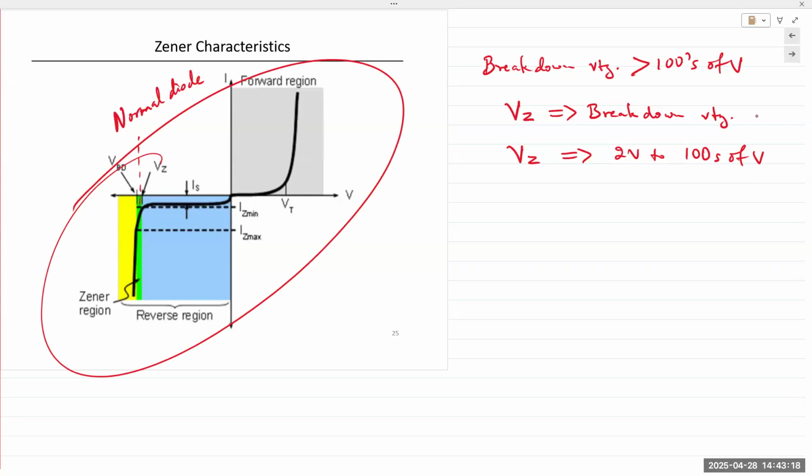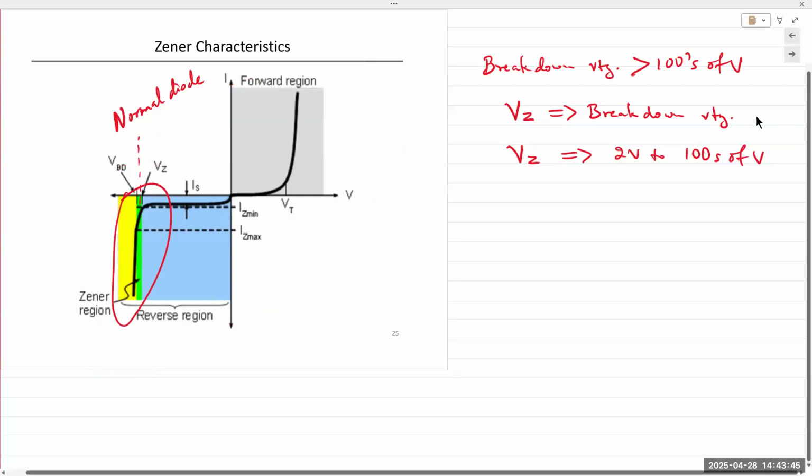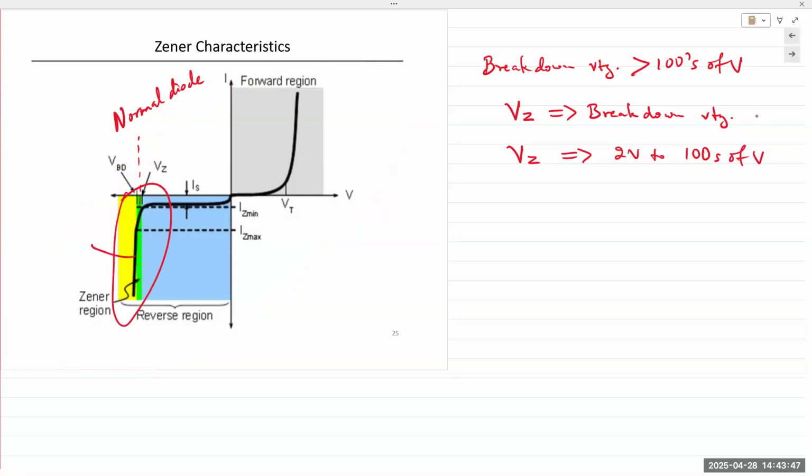It's one of the curious things about semiconductors. In the reverse bias, though, we can actually control the breakdown voltage. And that's the key thing. We can control the level at which the junction will break down. And once it breaks down, a diode will hold the voltage across itself constant. So again, whether it's a regular diode or whether it's a Zener diode, the voltage is held near constant.